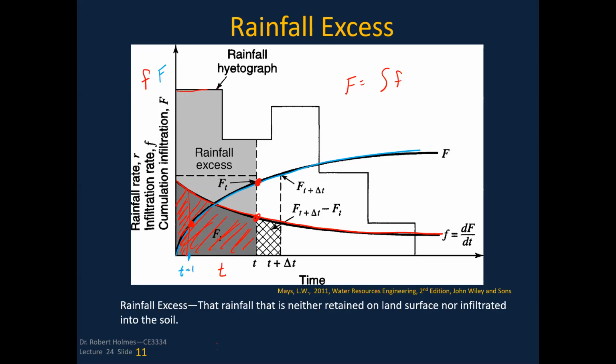And again, on top of this, we've got the hyetograph of rainfall that's laid out here. And so if this is my rate of rainfall I, let's change that color there, where you can see that maybe a little better. We'll change that to green. So if I've got a value of the rain that's in I, here is my rate of rainfall for this time period. The difference between the intensity of the rain minus, let's take the average infiltration rate across there. That above it would be my rainfall excess, and that below it would be the amount that is infiltrated.